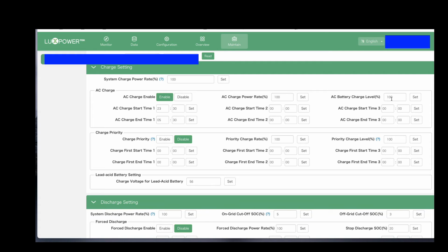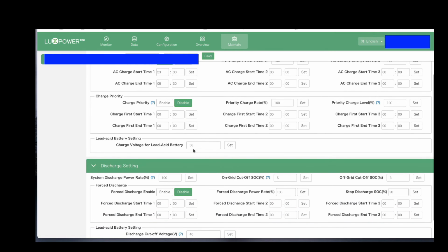He uses the off-peak energy in the morning rather than having to pay the full grid price. Then once mid-afternoon kicks in, the solar will charge the batteries up to 100%, and he can then use that energy in the evening. So he's using a combination of low off-peak rates plus solar to get the benefit, so he doesn't have to pay the peak energy prices.